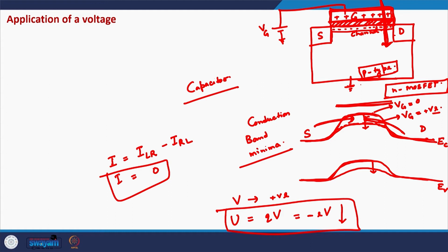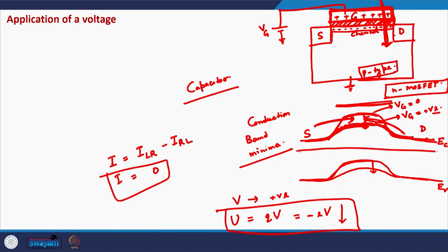So if there is any positive voltage on the gate terminal, it will uniformly lower the barrier in the channel. So it will allow electrons from both sides to cross the barrier with equal chances. So the Fermi level in the device will not change actually. It will be a single, uniform Fermi level across the entire device from source to the drain side. So that is essentially the effect of applying a gate voltage in the MOSFET.